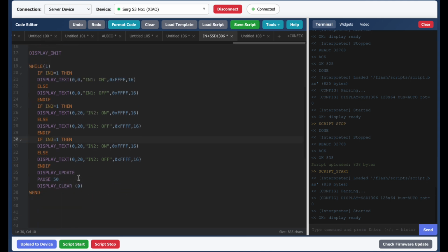When a finger gets close to or touches the electrode, the capacitance of the circuit changes, and the ESP32 detects it. The key advantage is that you don't need to touch the metal directly. The electrode can be hidden inside an enclosure with plastic or glass up to 2 or 3 millimeters thick on the outside. A touch on the surface will still register.